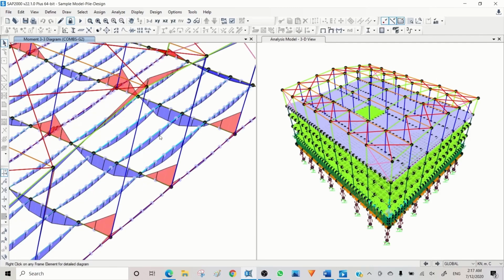The result is when we want to design a composite beam, we need to model that part of a slab as a flange on top of the beam, and that can be used for deflection and we can get the right moment, and the slab stiffness should be very small amount. So these are the realistic numbers we have for displacement and also for getting the moment.